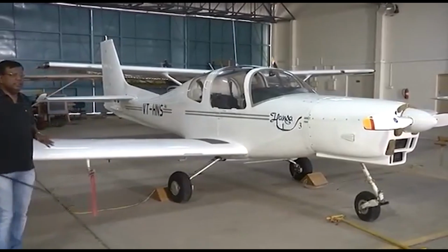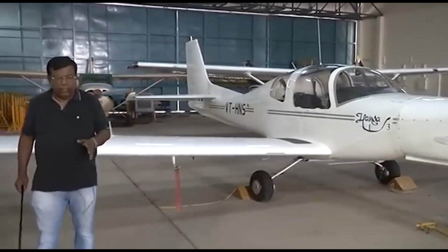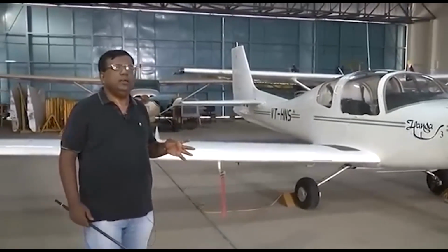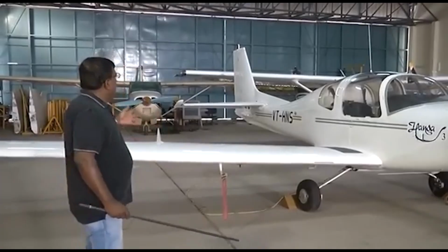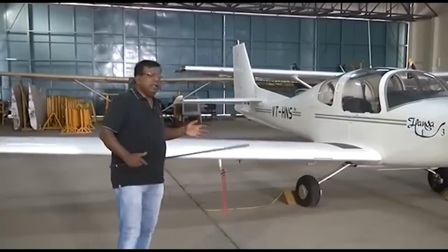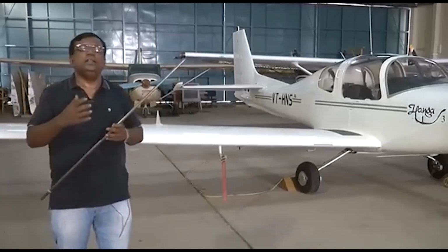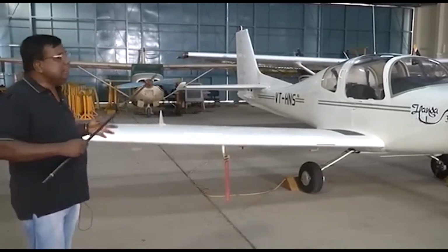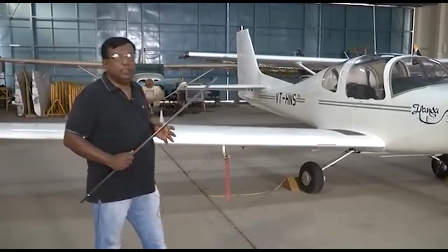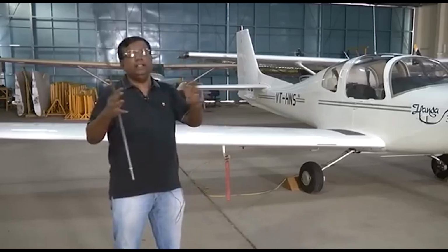But when I am talking about forces separately on fuselage, on wing, on horizontal tail, and trying to add them with a lot of care, because I know there is an interference effect, right? This method is called the component build-up method. That is, you find out the component and then add.